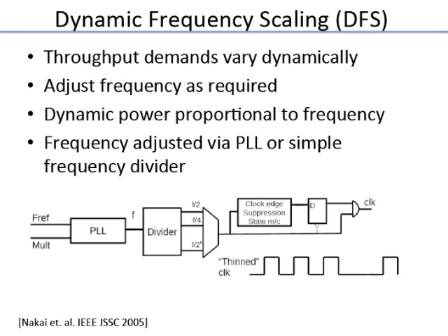That is one way, but it turns out PLLs have time constants in the kilohertz, perhaps megahertz range. So it takes a while for a PLL: if you change the divider ratio, the multiplication factor, it takes a while for it to adjust. For that time you have to just be waiting. It can take microseconds, milliseconds, depending on the PLL design.